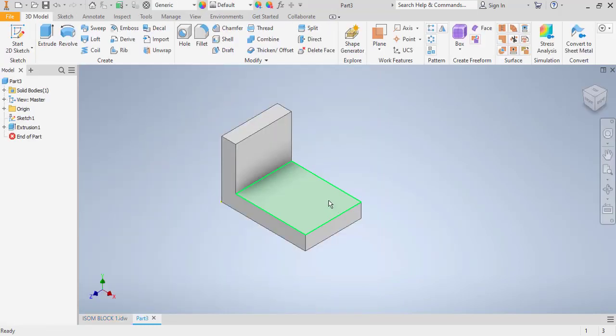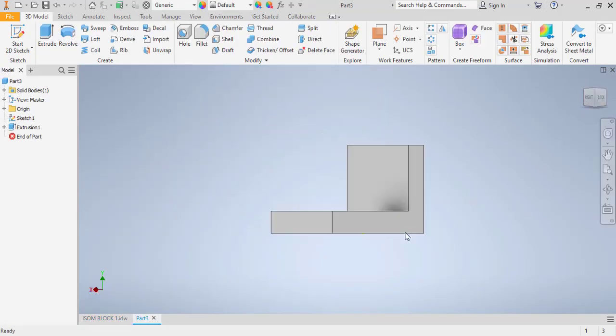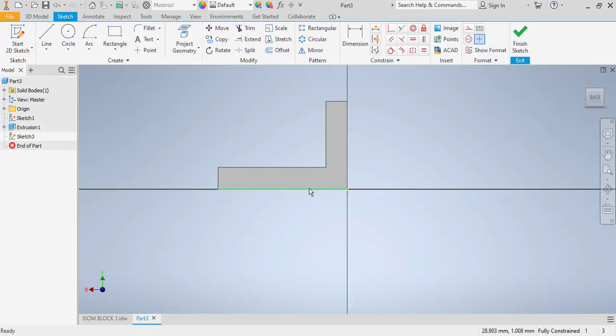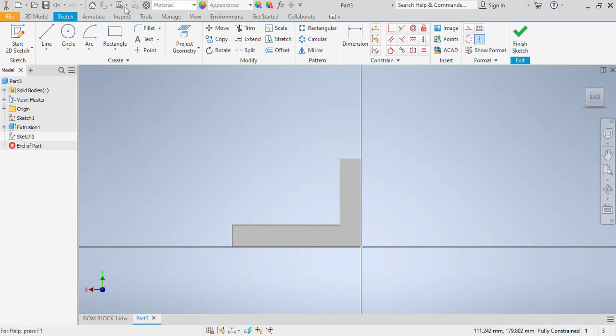Now straight away I'll go to the drawing, rotate it, and I want this part. So when you select this surface and click on sketch, and it's a new sketch now, in this case, click on align, and you start by drawing the height of this, which was 28.